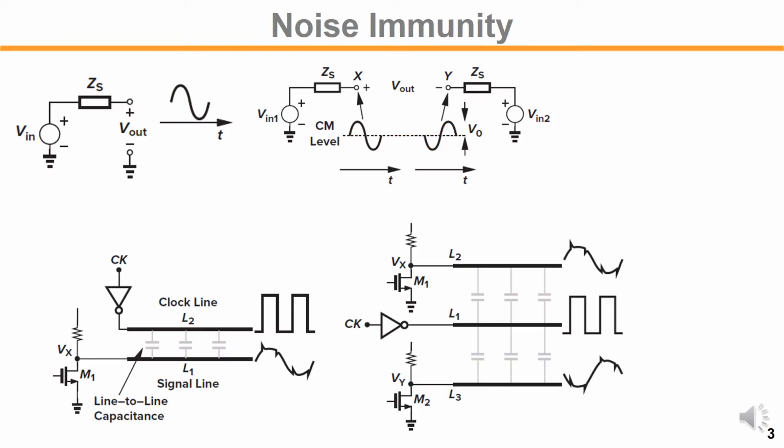An example of the noise can be shown here. Let's say, for example, there's a clock signal running nearby. So a clock is typically a square wave like that. If there is any coupling capacitance like this, that kind of coupling will result in a noise spike on our signal, right? Every time the clock makes its transition, the coupling appears on our signal.